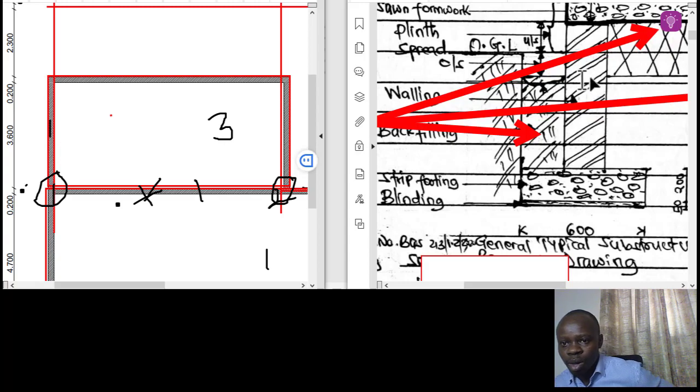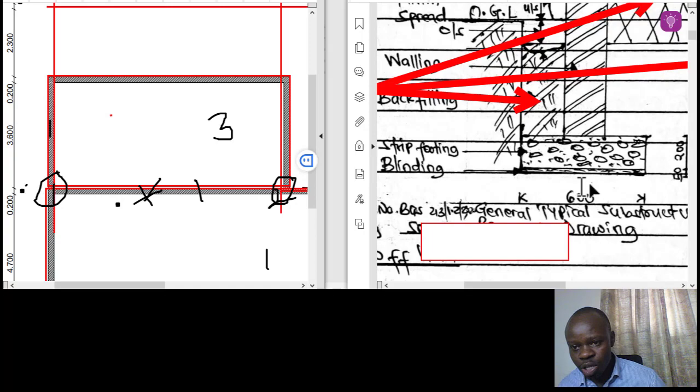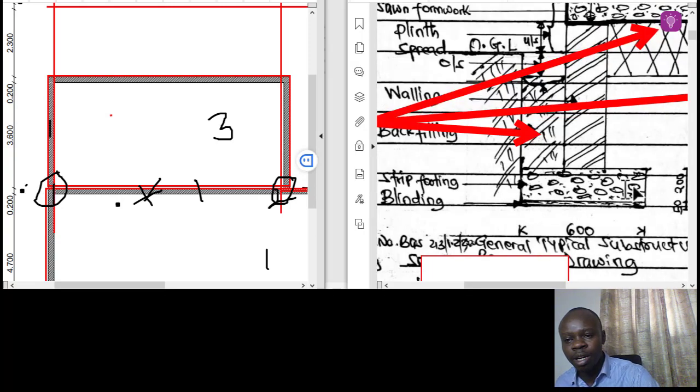So the same wall, but then the volume that we need is where we have the lower arrow. To the right, when you get to the left, that particular point should be the length that we are going to use, should be the center of it. So our foundation strip is 600 millimeters wide. Internal spread is 200, wall is 200 wide, and the external spread is also 200 wide.